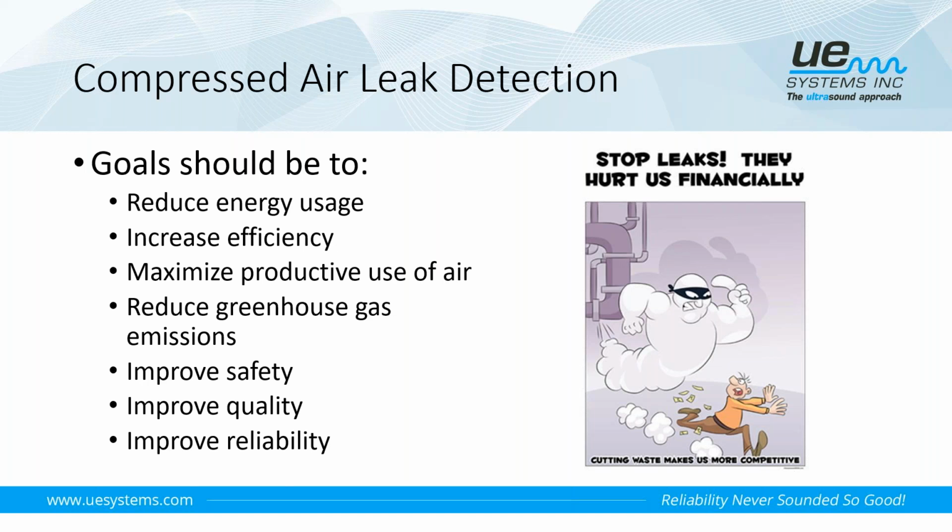When demand starts to creep up to whatever the maximum capacity is on the system, a lot of times, a lot of talk is given to having to rent compressors, bring in other compressors or install additional compressors. But again, a lot of times those types of investments can be nixed by simply locating and repairing compressed air leaks. That also helps us to maximize the most productive use of the air. We talked about greenhouse gas emissions, so we have ways that we can track that. Once we repair those leaks, we can see how much we've reduced our carbon footprint by.